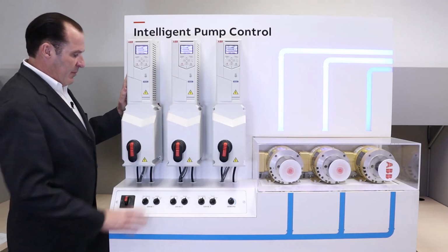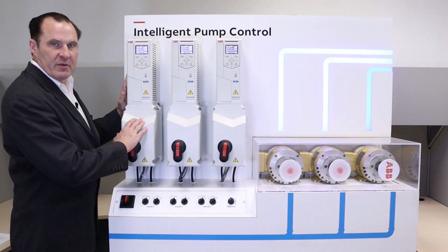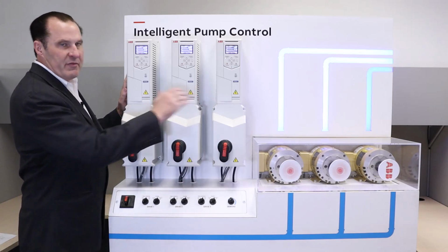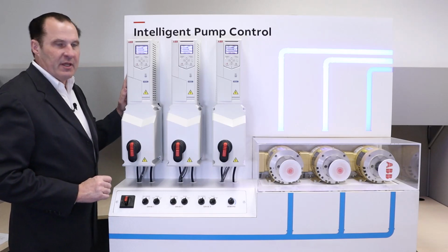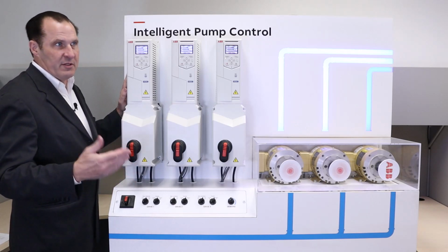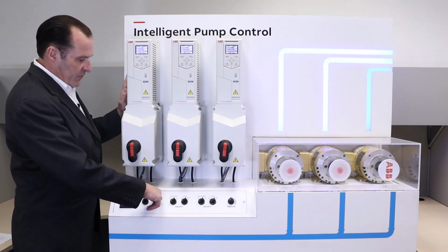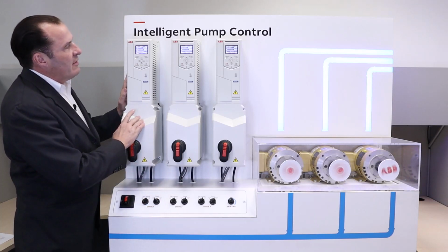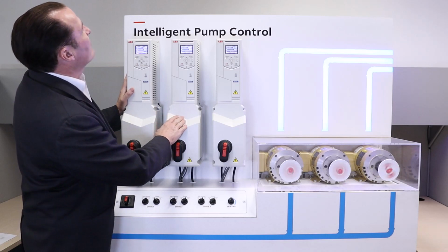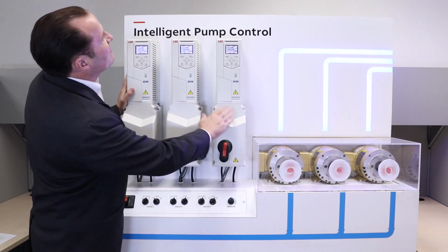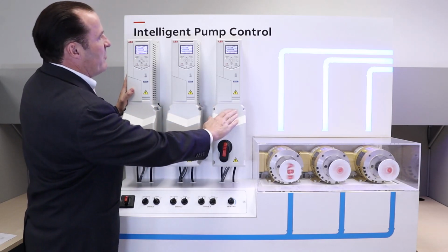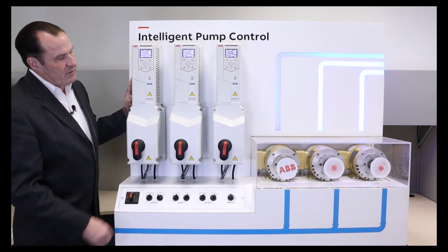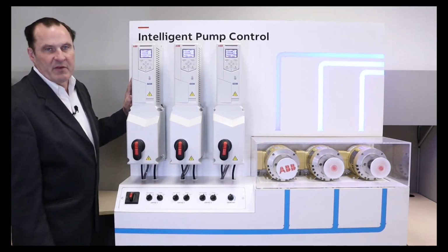I am going to fault the master drive, and with the moving master strategy, drive 2 or drive 3 will pick up the master position. It depends on where in the queue on the system they're at. So I'm going to fault it right now. I'm faulting drive 1. I've faulted drive 1. It's now faulted. And when I look here, drive 2 is follower, and drive 3 has become the master. So the master drive has moved over to drive 3. As we look at the motors, drive 1 is stopped, drive 2 and 3 have picked up the work.